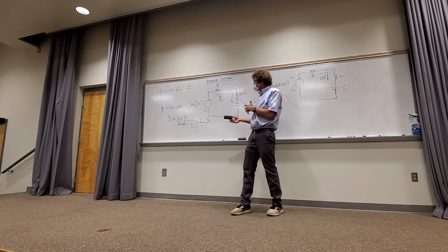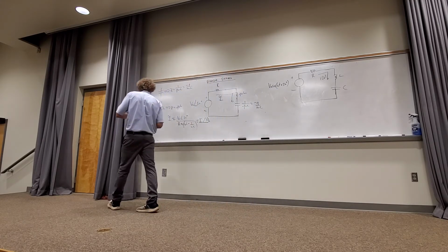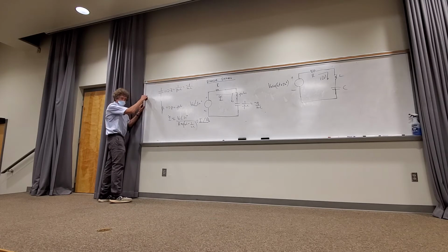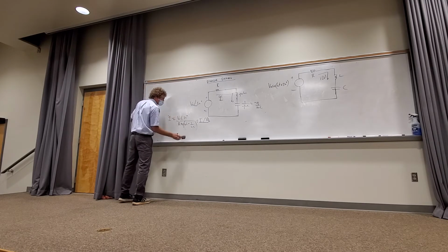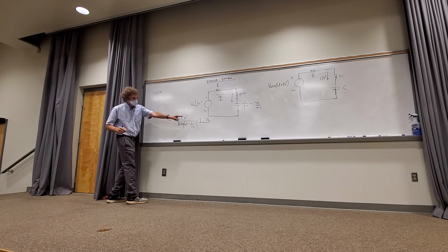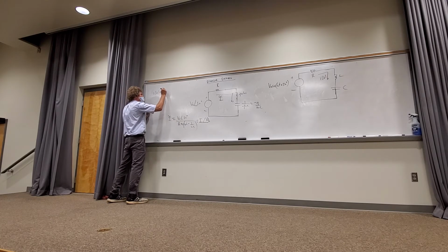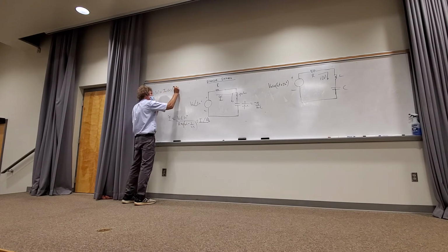That's still valuable. You've got the magnitude of I naught, which is usually what you want. In the time domain, if we go back and I wanted I of t, you simply take the scale value, the I naught, the magnitude. Then you take the cosine of omega t, and then you add this angle.